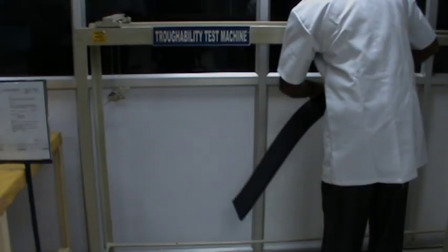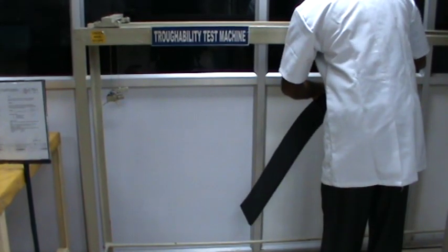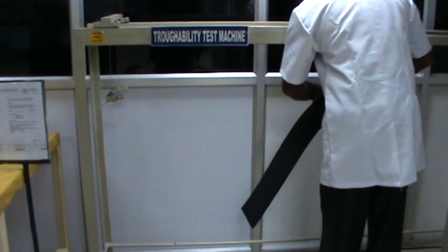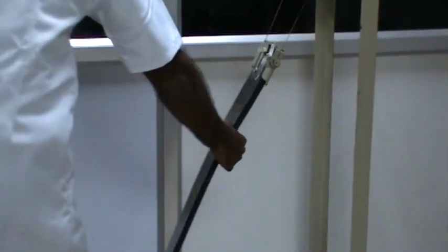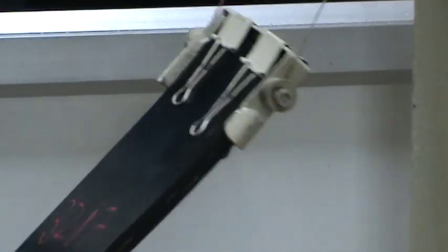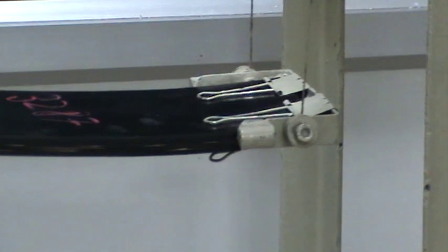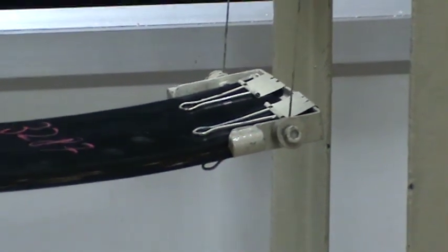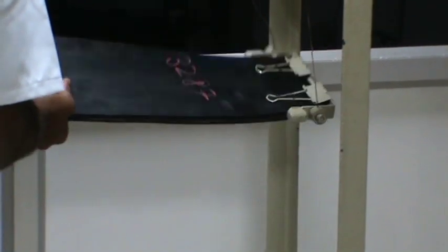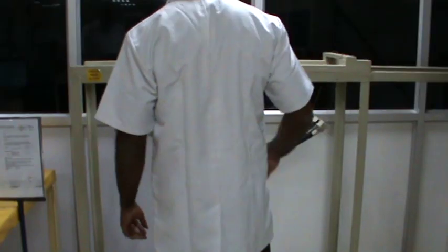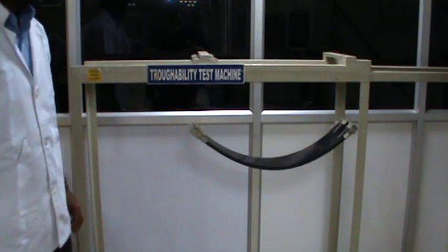H. Troughability. The ability of a conveyor belt to form a trough is measured by a device called a troughability tester. The troughability ratio, or factor, is expressed as a ratio of the amount a belt deflects when in free suspension, divided by the width of the belt in the flat position. This determines the stiffness of a conveyor belt, and therefore its suitability to carry a particular load over a specifically designed system. Problems can result if the belt is not of correct troughability.